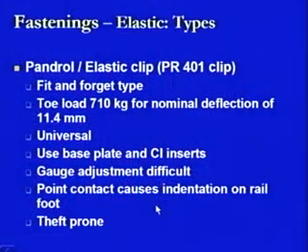Another problem associated with Pandrol clips is that they are theft prone. People can take them out very easily, because only the CI inserts have to be taken out, and as soon as the inserts have been taken out, we can easily take out the Pandrol clips.